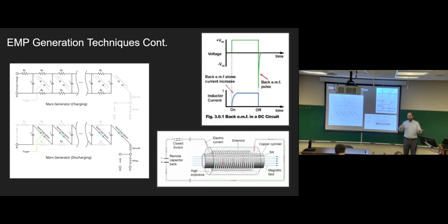So basically a good way to think about it: as frequency increases, a capacitor goes from being an open circuit to a closed circuit. And for an inductor, as frequency increases, it goes from being a closed circuit to an open circuit. They're the opposites of one another. And that's a very useful piece of information to know from a circuit design perspective. That's how you build things like oscillators, which are the basis of functionally all modern technologies. So it's good stuff. And inductors are awesome. They're cheap. They're one of the only components you can make well on your own. You just legitimately buy a wire and coil it. The formulas are very simple. They actually just ask how many times do you coil it, and that's it, which is nice.